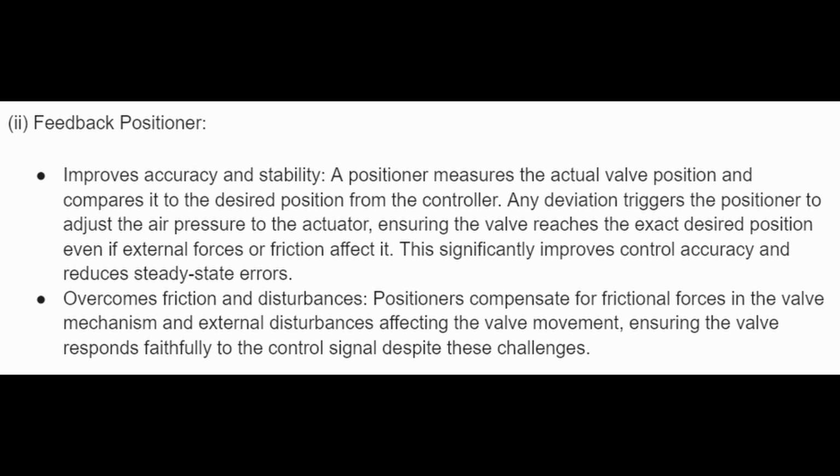Overcomes friction and disturbances. Positioners compensate for frictional forces in the valve mechanism and external disturbances affecting the valve movement, ensuring the valve responds faithfully to the control signal despite these challenges.